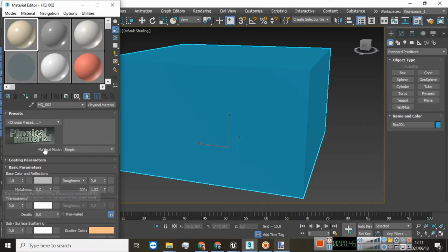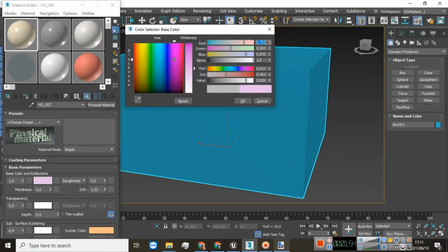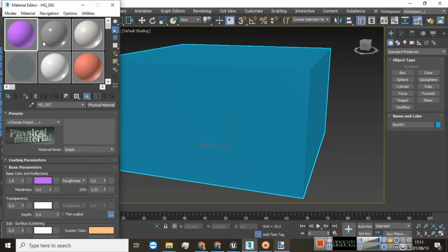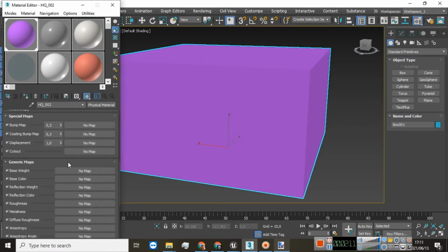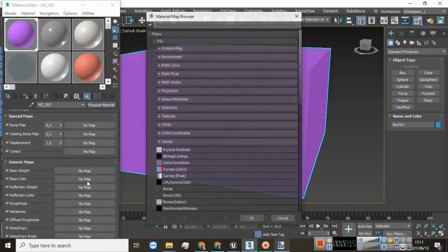So I'm going to put that texture I just made into that material by scrolling down, and there's the block I refer to. You can choose a color from that block anywhere and assign it to each of those models there on top. There's the color carousel, so just look for the first white block you see when you scroll down on a material, and you can pick a color. If you pick that color, there's the color assign button, and as you can see, it gets assigned.